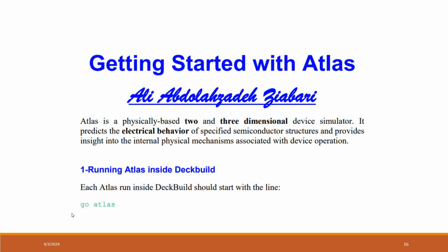Atlas is a physically based 2D and 3D device simulator. So in this tool, we can simulate 2D as well as 3D devices. Now, why do we do simulation? As I have already told you, it predicts the electrical behavior of a specified semiconductor structure and provides insight into the internal physical mechanisms associated with device operation. All of you know that part? Okay. Now let's begin. What is the main motto of this lecture?